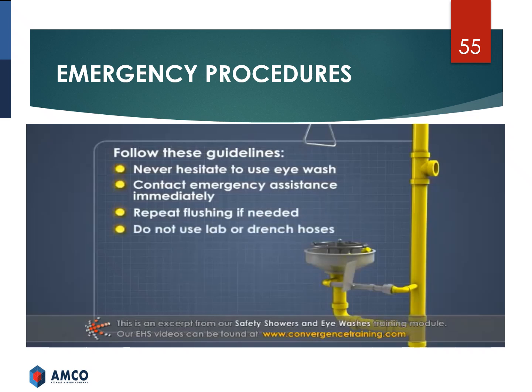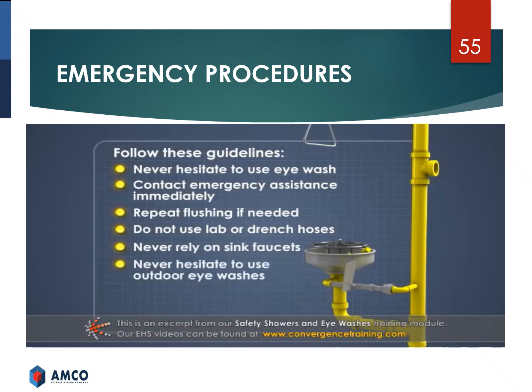Do not use lab or drench hoses as an eye wash. These hoses are typically used for cleaning and may not be sanitary. Never rely on sink faucets to replace an eye wash. Some outdoor eye washes may run discolored water for a few seconds. Never hesitate to use them immediately when needed. Do not use the shower for any other purpose that might inhibit the immediate use for an emergency. And beware of slippery floors during and after use.